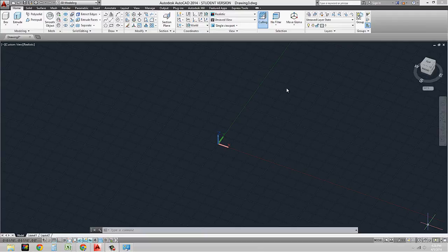Now, layering in 3D is also a tough thing to try to communicate to people, because it's not a plan, it's not an elevation, it's not a section, and really when you start to print it, it doesn't really matter about line weights. It mostly matters about objects. So what I always say is treat it like you would building a physical model. I think that's the best way to approach modeling in 3D, or at least that was the way that always helped me. And when you start to think about the layers, think about the elements that you're using.